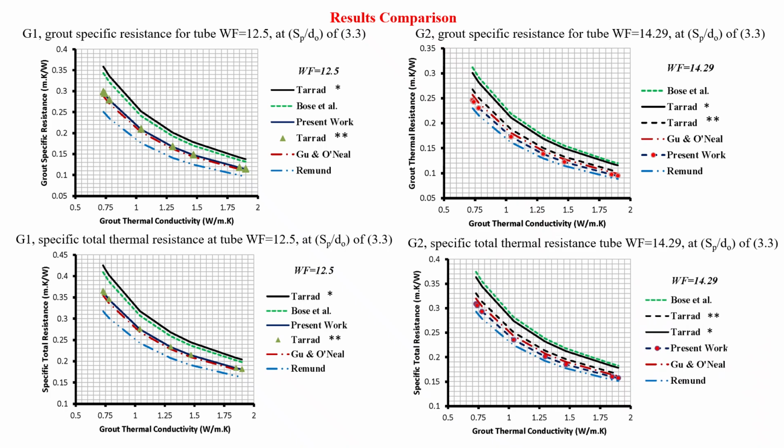And of course, these values should be used to predict the depth and the length of the heat exchanger, which can be used to achieve a certain cooling load, which represents the condensation load for the refrigerant Freon 410A, and mainly depends on the total heat transfer rate and the temperature difference between the fluid and the soil which surrounds the borehole.